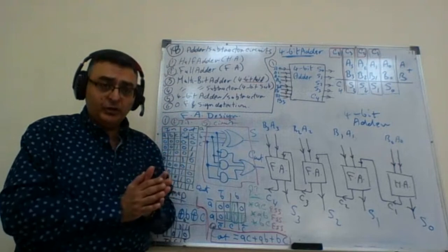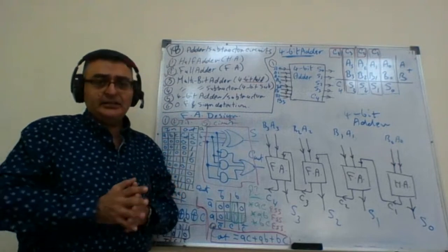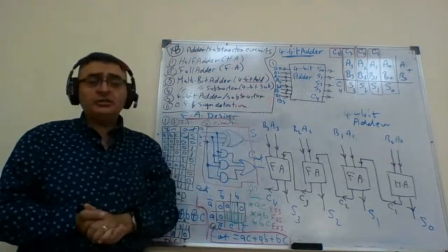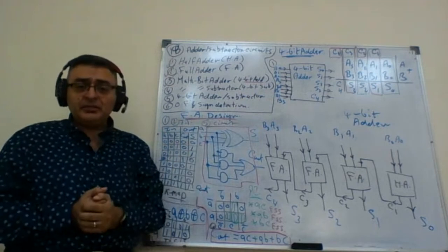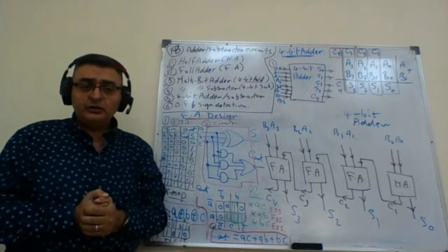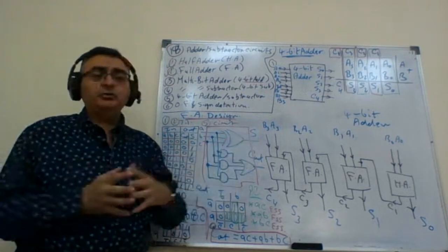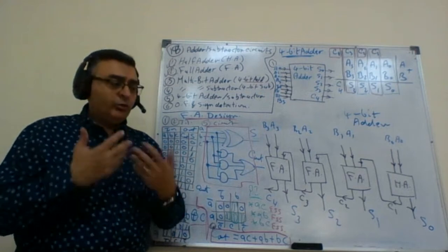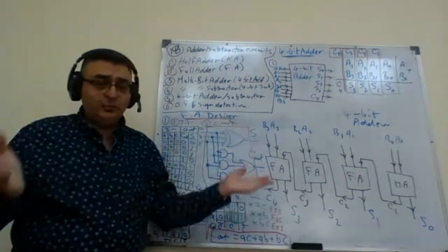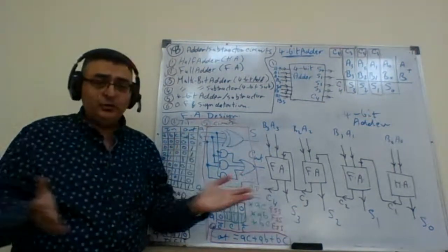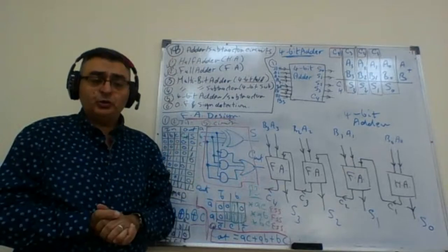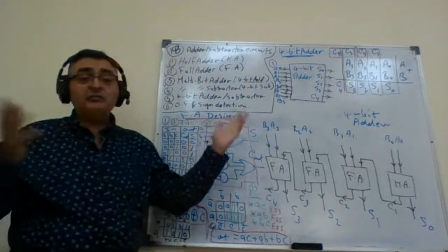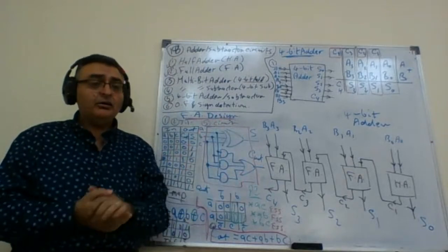The cons is that the design is not simple. The design needs some assistance of computer tools. It needs a significant amount of time in order to work with a truth table of 256 rows, working with 5 K-maps that are 8 variable dimensions.